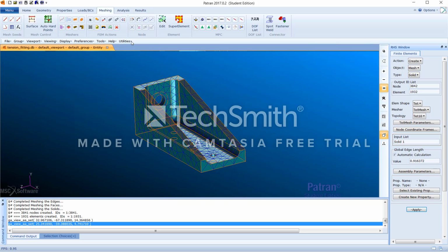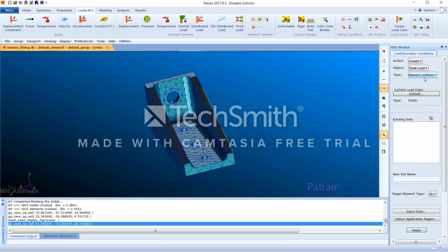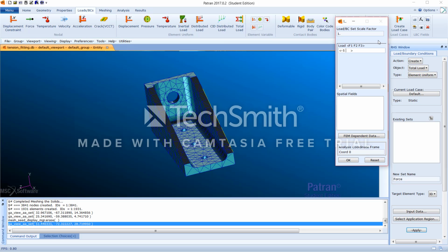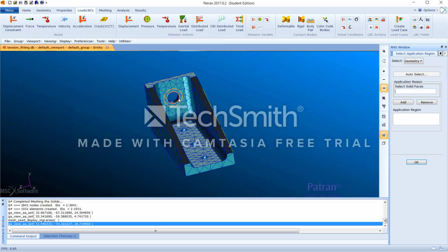In this step, we are going to create the loads and constraints. Set action as create, object as total loads, and type as element uniform. Enter force as the new set name and click input data. Enter minus 5000 for load and click OK. Click select application region. Select the vertical solid face created by imprinting at a larger hole and click add. Click OK and apply it.